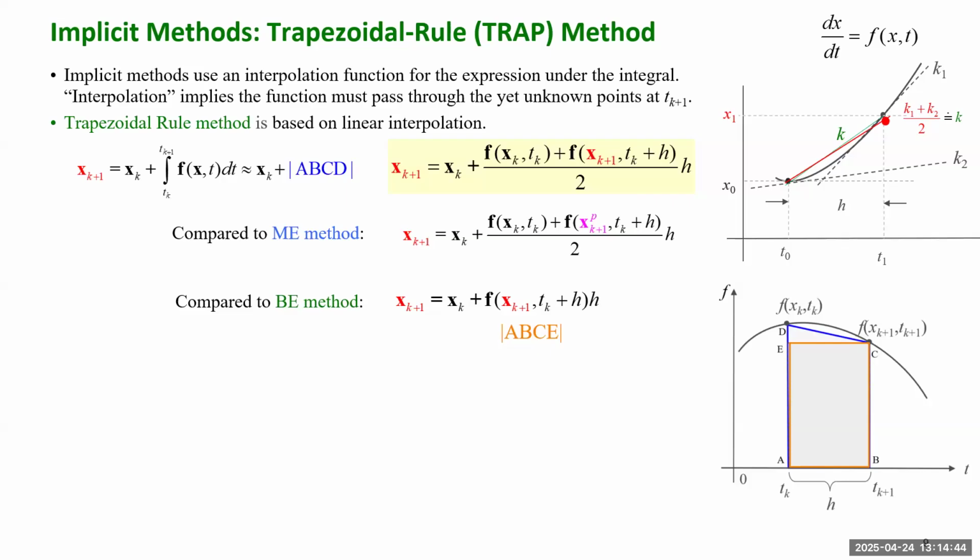Implicit methods have no numerical stability issues if the system is stable, which means the curve will be bounded. If your system behaves as a stable system, even if it oscillates near the equilibrium point, the simulation result based on the trapezoidal rule method will also show maybe an oscillatory curve near the equilibrium point.